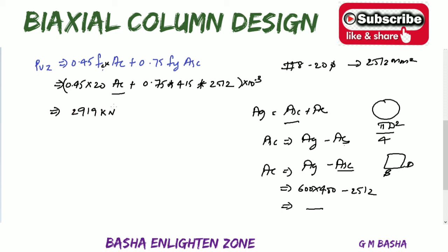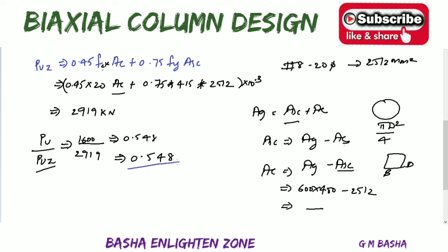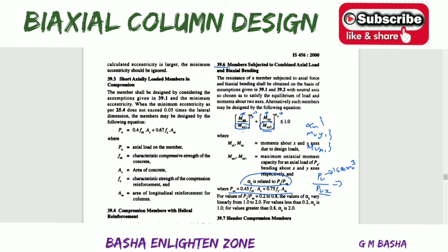Okay, then already you people know PU value, which is 1600 into 10 to the power of 3, or else it will be in terms of kilonewton only, no need to convert that one into Newton. Okay, then PUZ will be equal to 2919. If you simplify, you will get 0.548. So this is the value of 0.548. So the PU by PUZ value will be equal to 0.548. Okay, so what they told in the code, so based on this PU by PUZ, alpha n